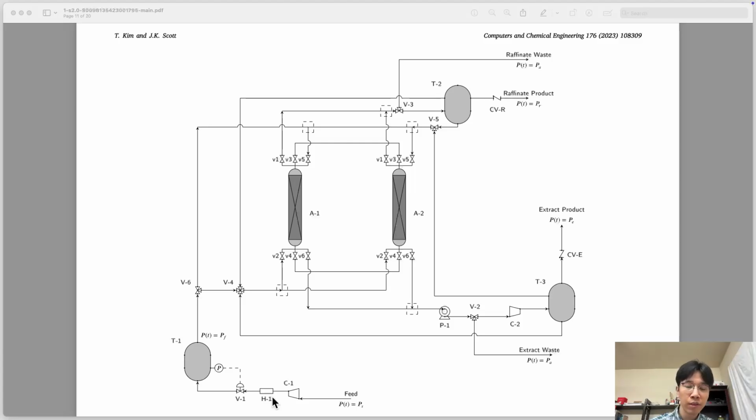So you need to exchange some heat to get the right temperature of your feed. And then we have this mass flow controller that gets the information about the current pressure level in the feed tank, and then controls the flow to maintain the pressure inside the feed tank at a fixed pressure, which we're naming PF.